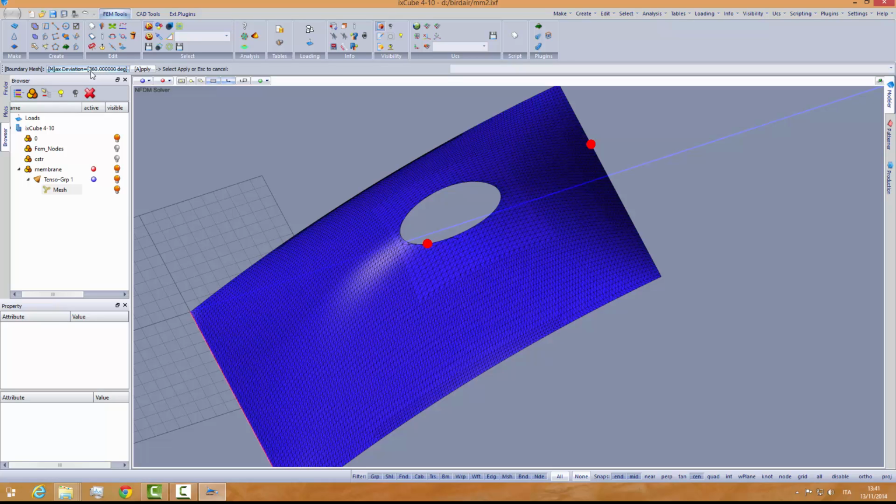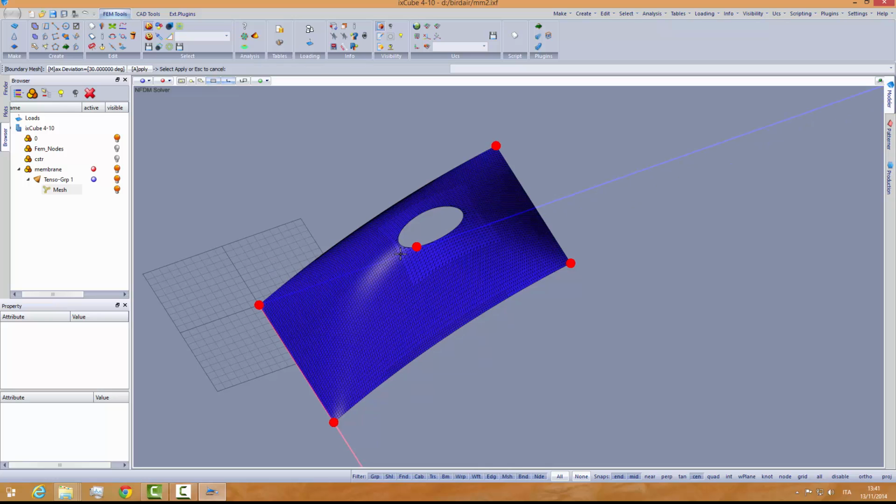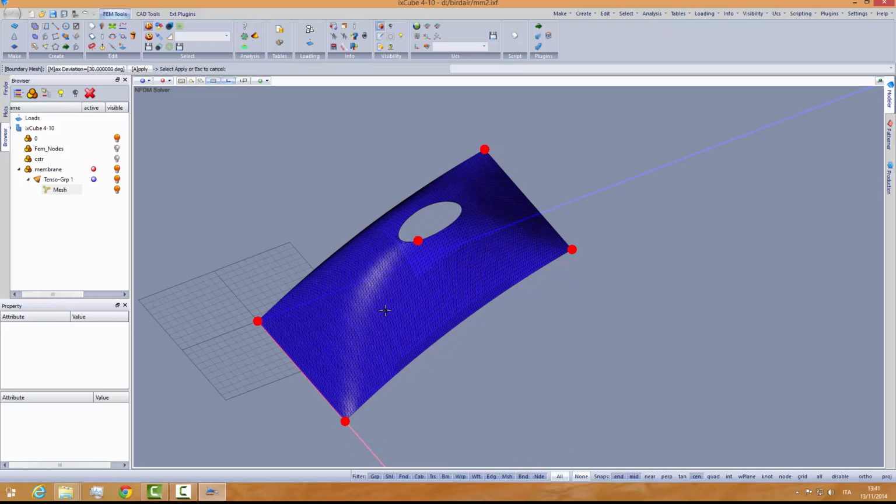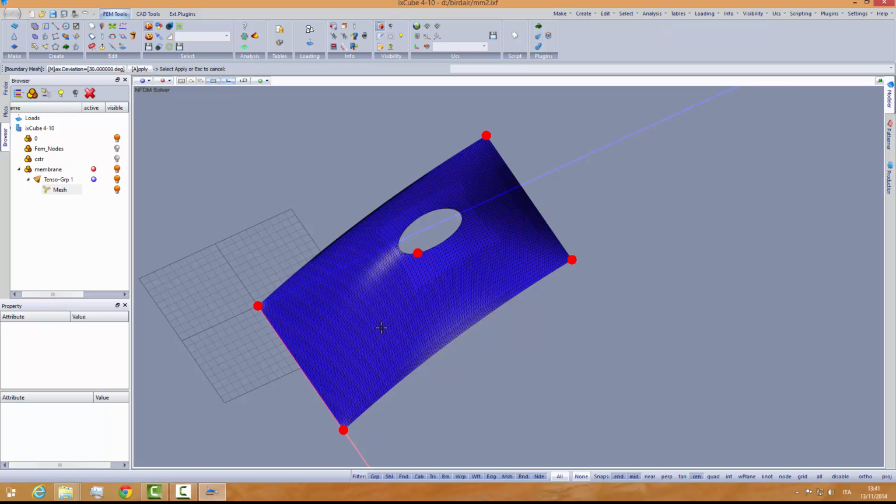It's 360 degrees. So let's change this to a small angle, 30 degrees. And that means when it detects a corner in the edge bigger than 30 degrees, split the edge at that point. So once you click enter, you see that it has recomputed the edges, and now I see 4 red dots. 4 red dots means that I will have one edge that goes from red dot to red dot, another one, and so on, up to 4. And of course one single loop in the elliptical ring. So if I am happy with this, click on apply, and we see that 4 edges have been created.